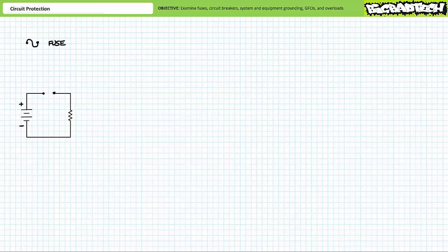The advantage of fuses is their incredibly simple operation principle. As long as the rated voltage and breaking capacity of the fuse is appropriate for the application, they are an inexpensive and reliable means of defense. This being said, a blown fuse is a non-reusable component. Because of this disadvantage, fuses often form the final but most reliable line of defense for circuit protection.